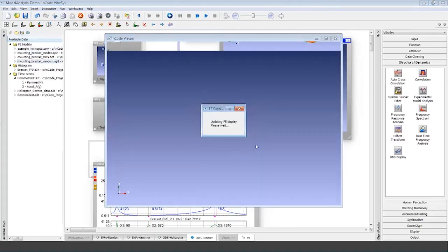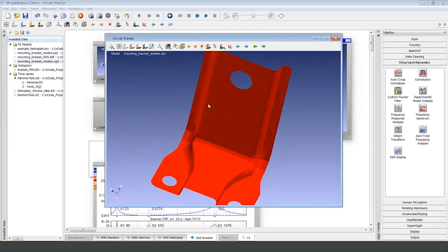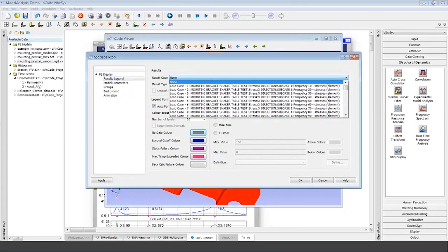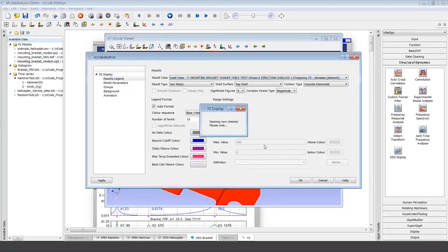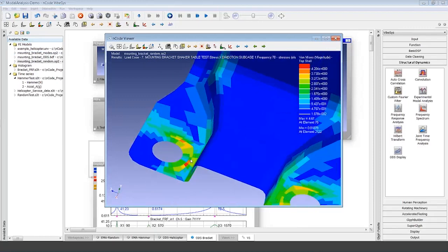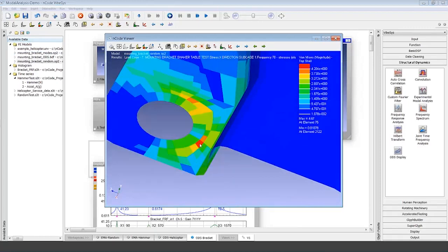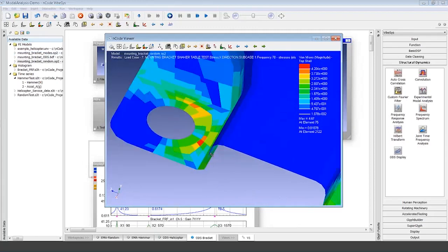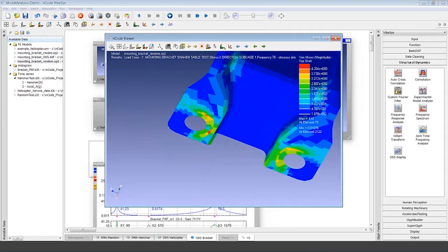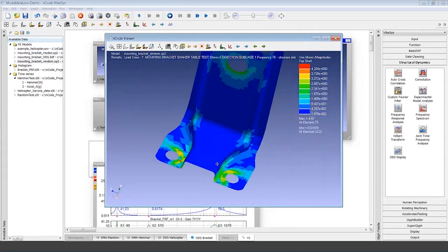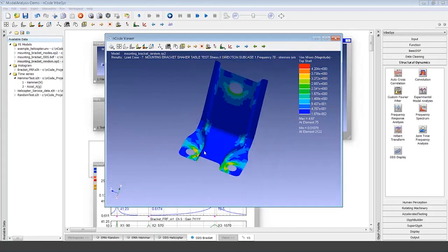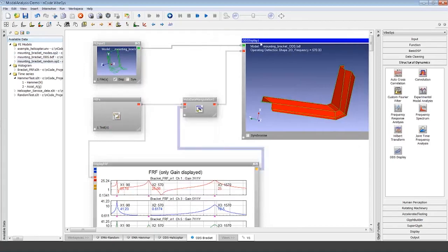For instance, for random fatigue analysis, you need some stresses at various frequencies. And as you can guess, once you look at the stress in this element, it's strongly dependent on the mode shapes, on the model behavior, on the dynamics of the structure. If the dynamics are wrong, the stresses will be completely wrong as well. So in order to have good confidence in your model, your results, and therefore your fatigue analysis and your design in general, I would strongly recommend comparing FEA with a simple model test. I think that's it.